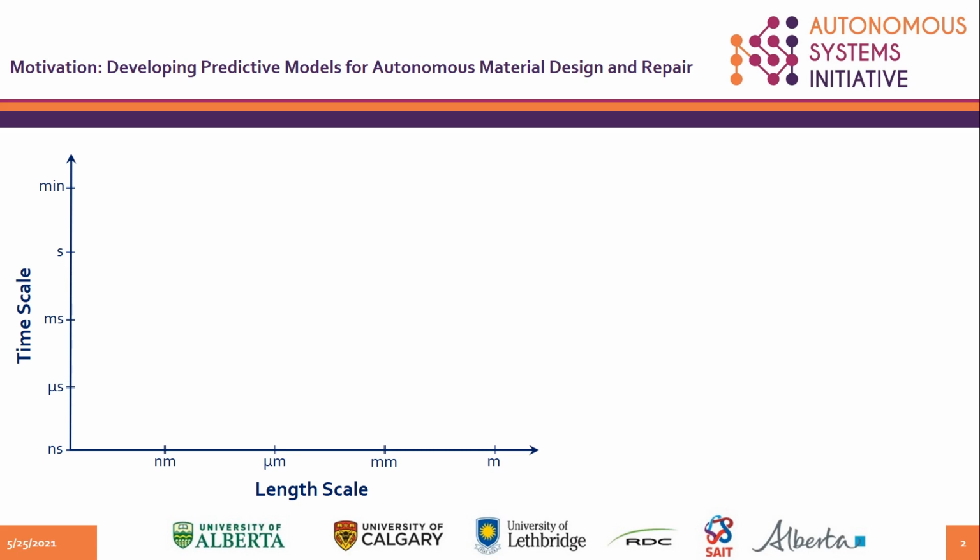To begin with, I want to show you the typical experimental efforts that we take to investigate the behavior of MMC coatings. Basically, we do nano and micro indentation to assess the effect of ceramic particles on the hardness of the metal matrix composite coatings, and plastic deformation of the matrix and particle fracture are the typical mechanisms that we observe.